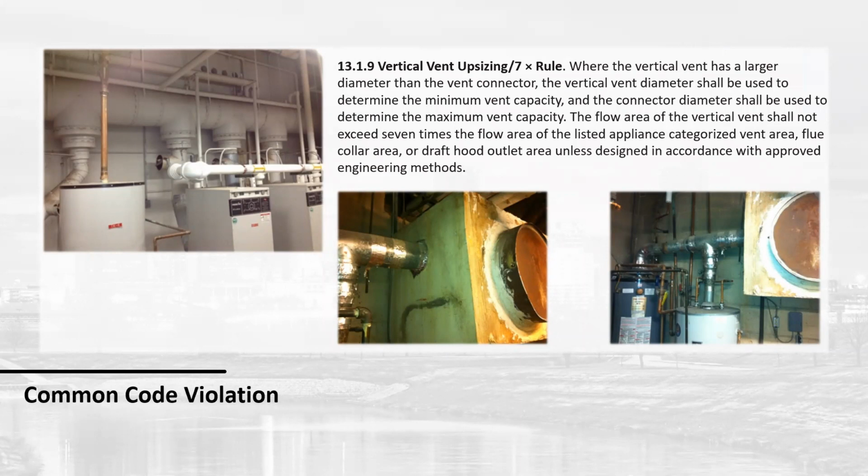But a lot of times we'll see this in school districts where they had an old big fire tube boiler that was doing everything, steam and indirect hot water and kitchen. And well, they've abandoned the kitchen and they've broken off the water heaters, put those in a corner for a little hand sink or something. And then they're replacing it with condensing boilers. Those are going sidewall, but they still have this 40-gallon water heater dumping into this brick chimney. And that's a no-no. So the way you get around that, put a fan on it. Again, we're mechanically inducing that draft.